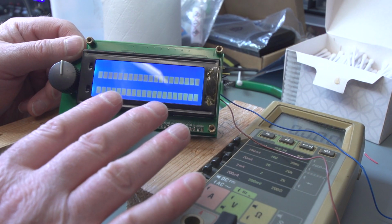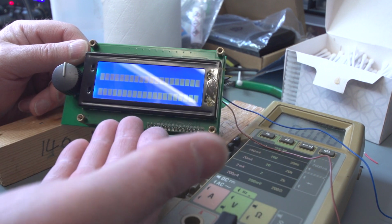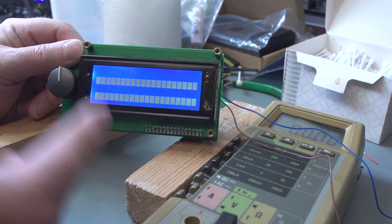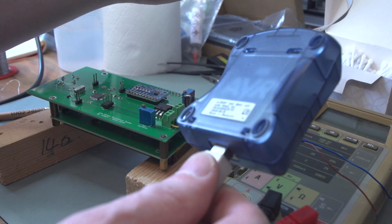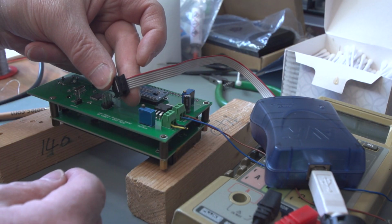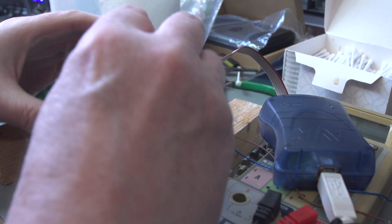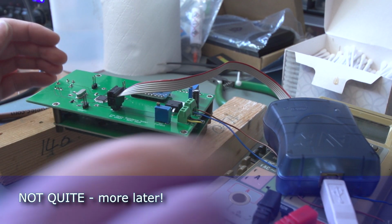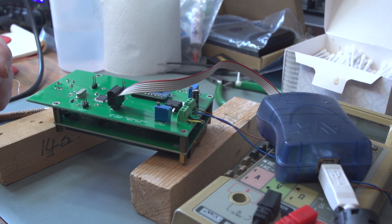So that means we've got power to the display. We know the contrast is working. Just a default going on at the moment. There's no firmware, so let's go over to the computer, see if we can get some firmware into the thing. So this is the programmer, AVR ISP Mark II, it says on the back. So we can plug in the programming lead into the ISP socket, making sure we get pin 1 located at pin 1, which is on the top, and that just plugs in there like that. So now we can go over to the computer and hopefully get some firmware going on here.